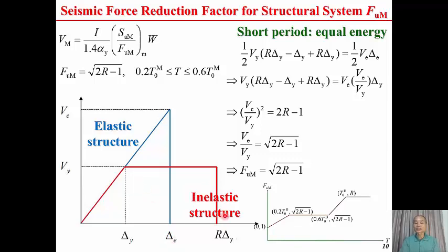For the inelastic structure, when the displacement becomes delta Y, the structure yields and remains at the force Vy. Therefore, it is simplified as an elastic, perfectly plastic structure.